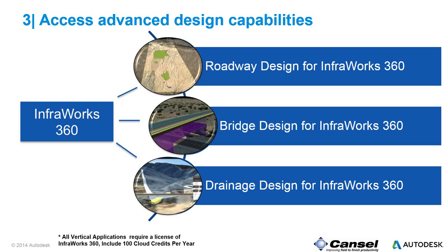For example, you're designing a subdivision, and you have a design road created with curbs. You can ask the software, please create a drainage design for me. You may be wondering, okay, how does the software know what to do? Well, when you create a road in Infraworks, you choose from different types of roads. You could pick a highway, a collector road, or a local road. And depending on the type of road you select, the appropriate design criteria file is used to manage that road.